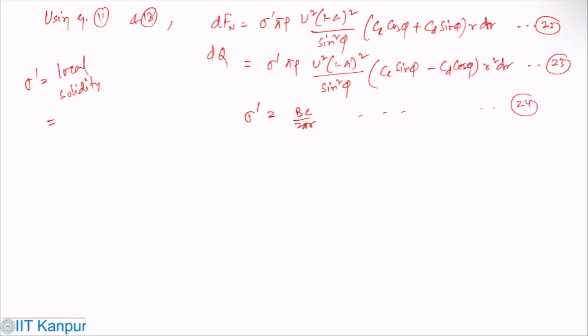So what happens is that, in general, in the calculation of the induction factors a and a prime, this is the practice: to find a prime, we set CD equals 0. For airfoils with low drag coefficient, this simplification introduces negligible errors.